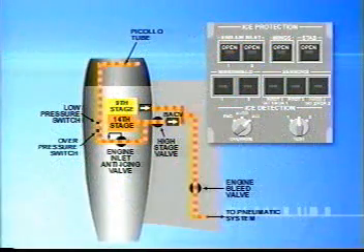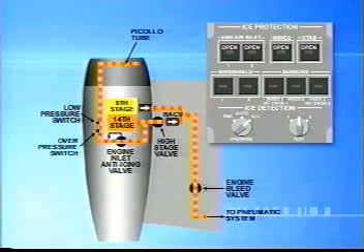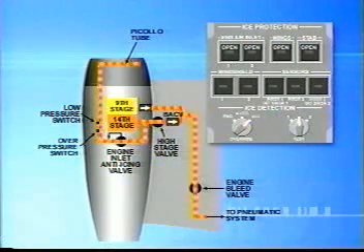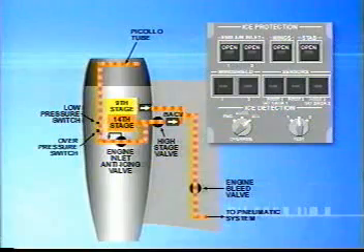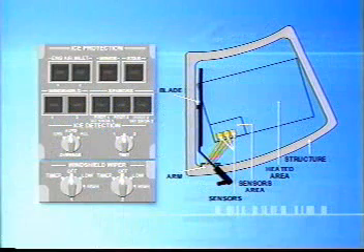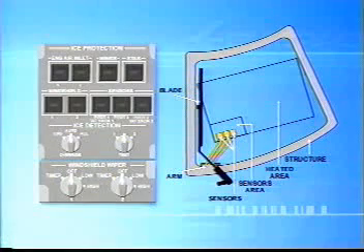The engine anti-ice system may be operated on the ground or in flight. When the system is on, the anti-ice valve is open, which allows hot air from the engine high-pressure port to be supplied to the cowl lip. The windshields are electrically heated for anti-icing and anti-fogging purposes. The system should be selected on whenever outside air temperature is below 10 degrees Celsius.